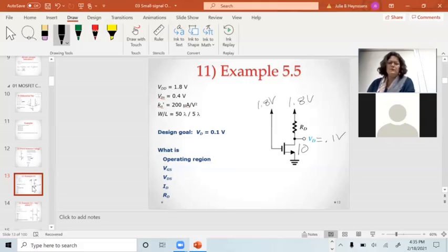This is something you'd use, say, if you had an Arduino output and you wanted to turn power on to a circuit and run it from a separate supply. So the power's coming from here, but the control's coming from here. We'll do this. This is like the first project in 490 in the fall. Control. And that is a series pass transistor.